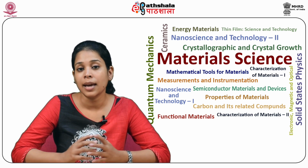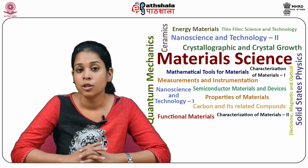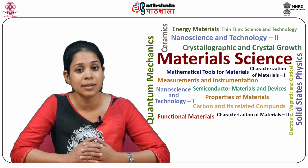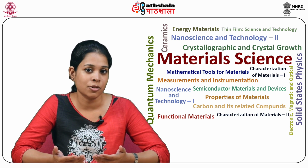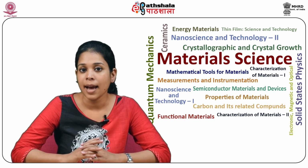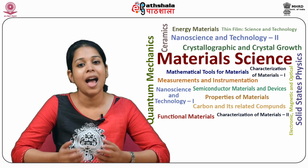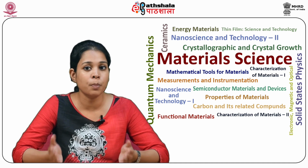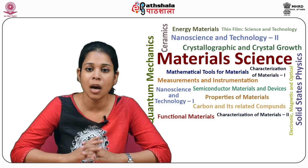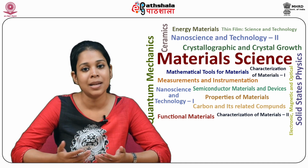A vacancy, or a pair of vacancies in an ionic solid, is sometimes called a Schottky defect, and another defect is the interstitial defect. Interstitial defects are atoms that occupy a site in the crystal structure at which there is usually not an atom. They are generally high energy configurations, and small atoms in large crystals can occupy interstices without high energy, such as hydrogen in palladium.